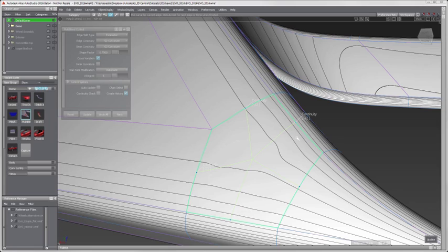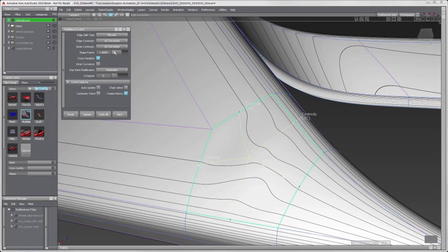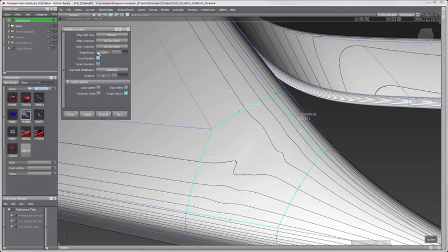There are several options for the edge split type. Parameter places the surface boundaries in the middle of the curve. User Defined lets you manually control the position of the edges. Flexure is similar to curvature, but adds additional math properties. Arc length places the boundaries in the middle of the chord.